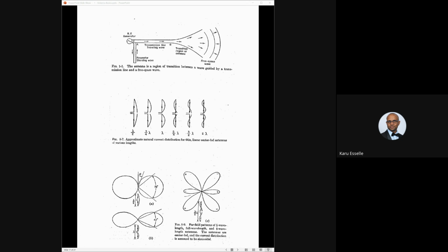So with half the size, you still have an antenna that is reasonably good, but it needs this conducting ground plane. It is useful in some tall antennas, especially at lower frequencies. The dipoles are very tall, and you can use the ground as a conducting plane.